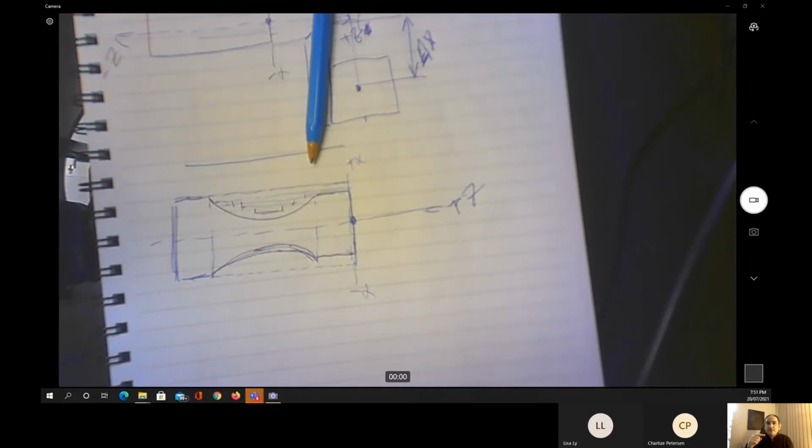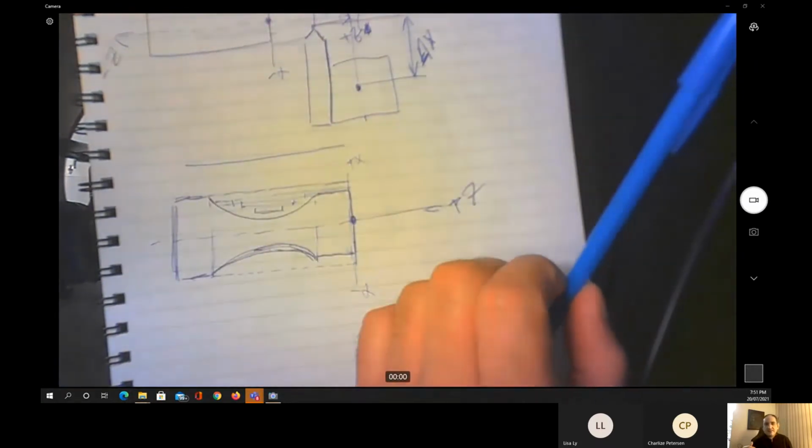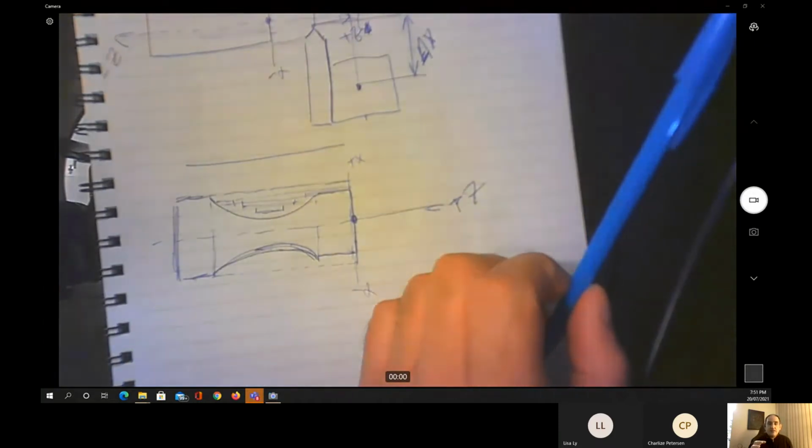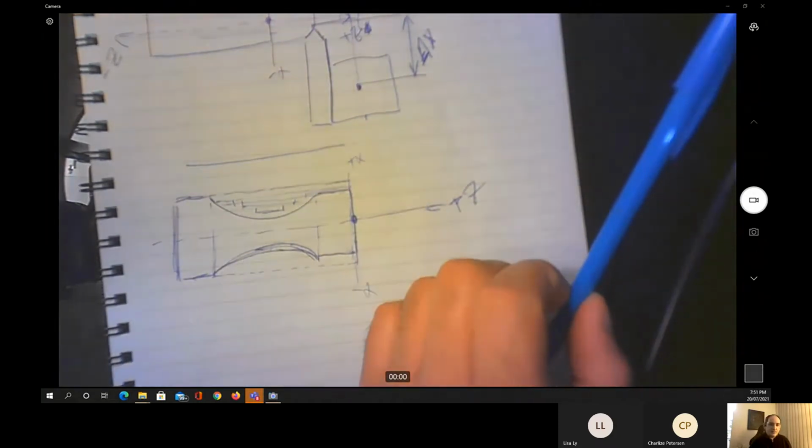In the case of the finish cutting, the RPM is going to increase, the feed rate is going to go slower, and the depth of the cut is going to be less. We can do the calculation for that. I think we learned how to do that in manufacturing engineering. Later, I'm going to show you how to do this approach in the CAD/CAM, but this will be a common session between the students who are attending this session but not doing advanced manufacturing. Anyway, it's going to be part of the advanced manufacturing subject.